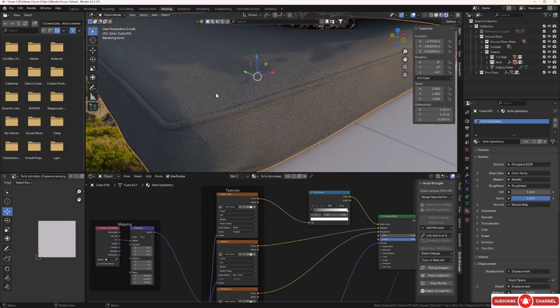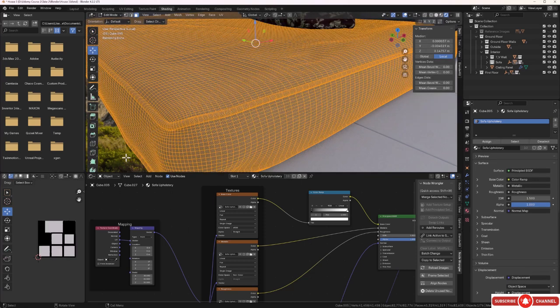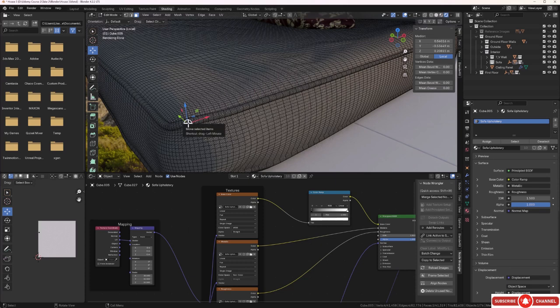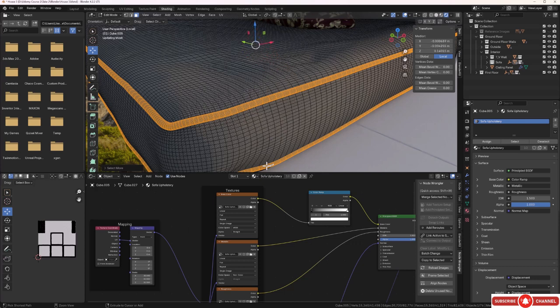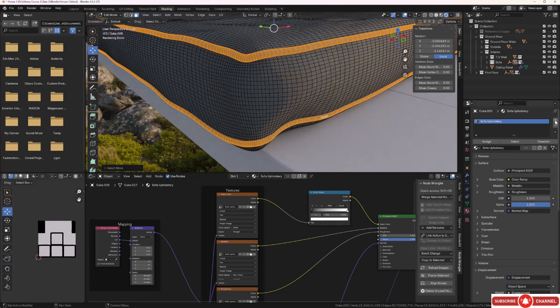Anyway, let's tap in and let's deselect everything and then just grab one on this one, hold shift and grab one on the lower piping, hold control and plus and expand on that selection. And when that cursor stops moving, it's a good indicator we've selected all the piping. And now that we've done that, let's go ahead and hit the plus key over here.